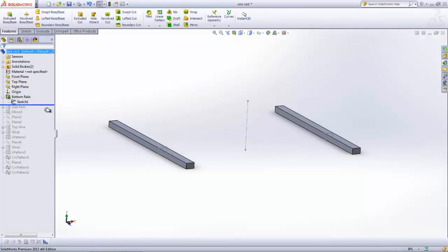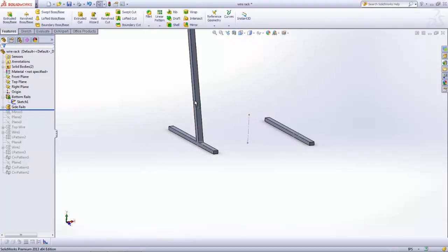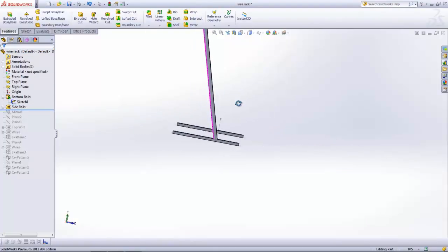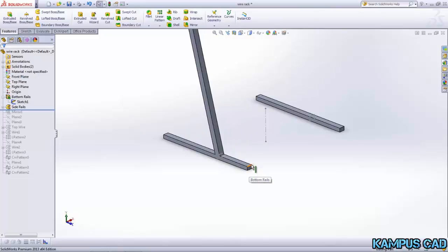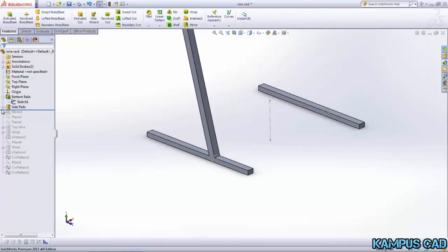So next, I made the side. Now if you're going to keep it boxy, you could have drawn it as an extrude over here. But if you're going to round it, like I suggest if you want these edges rounded, I would probably add fillets in my sketch. You would have to use a sweep.